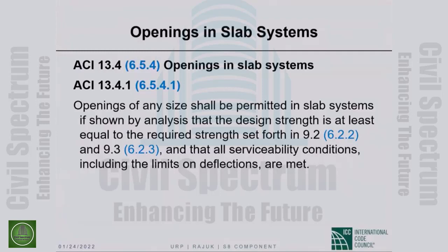Openings in slab. Openings of any size shall be permitted if shown by analysis that the design strength is at least equal to required strength and that serviceability conditions are met.